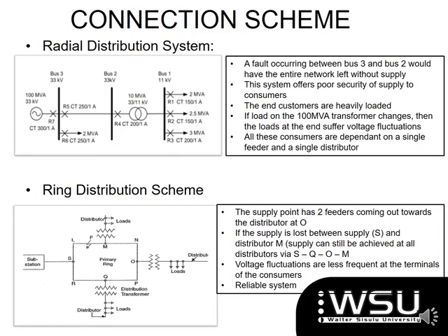At that point, you then go into what we call your distributor, so that you have lines coming out that are 2.5 and 3 MVA. So that's a radial. You're moving from your supply source directly to where your loads are, and your loads are those 2.5 and 3 MVA at the end.